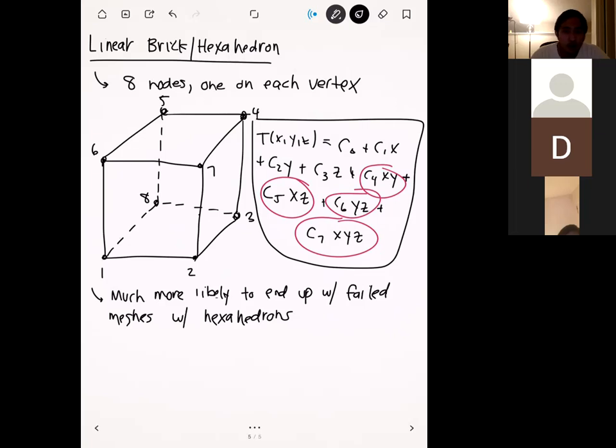You might be wondering, why did some people have issues with the hexahedral mesh, but some people didn't? It's a good question. The reason is that meshing is not an exact process, and every computer will usually mesh something a little bit differently. The way meshing typically works is that you take your CAD geometry and it finds where all the solid parts are, and it semi-randomly puts points. It starts by populating your geometry with a bunch of little points, and then it tries to connect them together into elements. Because there's that little bit of randomness, every computer does it a little bit differently.